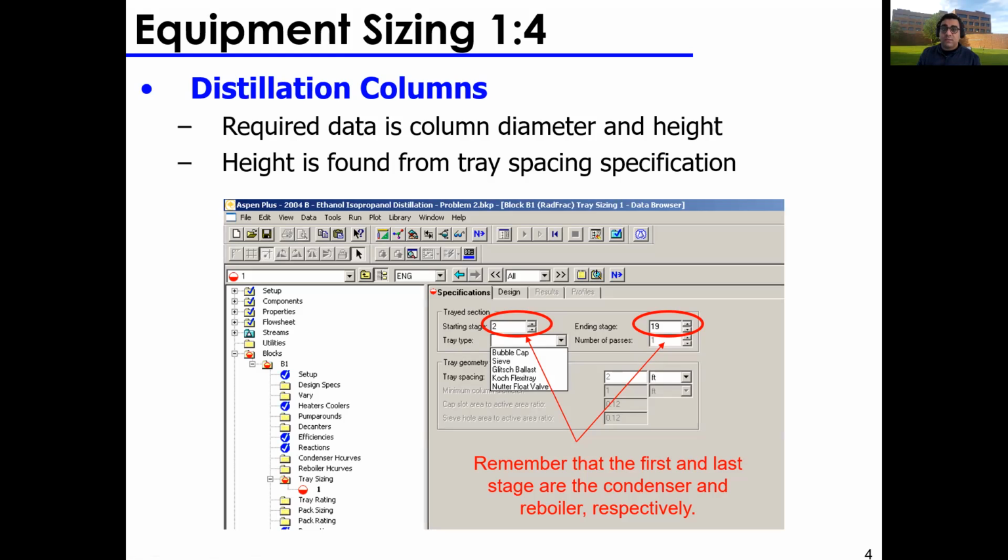The first thing is assume an efficiency for every stage. So if you say I have 30 equilibrium stages using McCabe-Thiele, very ideal case, everything is nice. However, I'm gonna assume that each stage operates with an efficiency of 70%. And now you adjust your number of stages. So if you have 30 stages, each stage operates at an efficiency of 70%, your new number of stages will be 30 divided by 0.7, which is 43 stages, okay? This will be the actual number of stages you're gonna use.